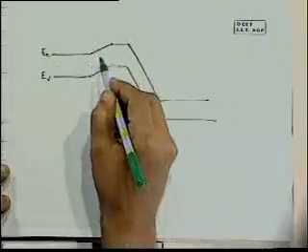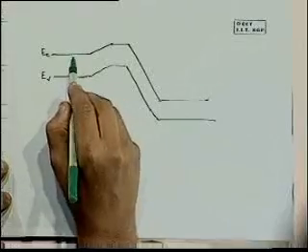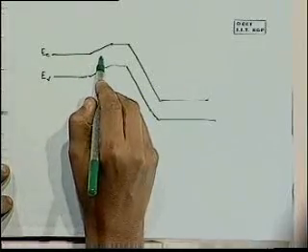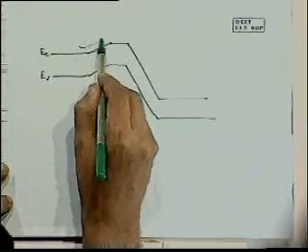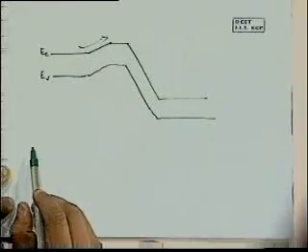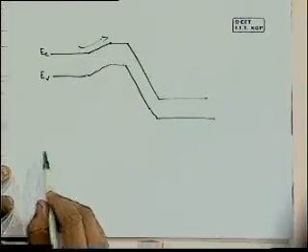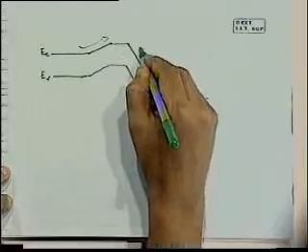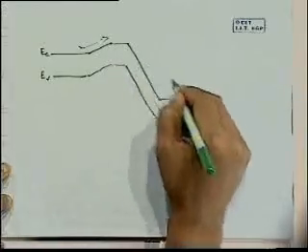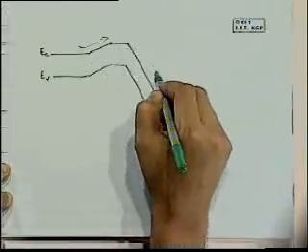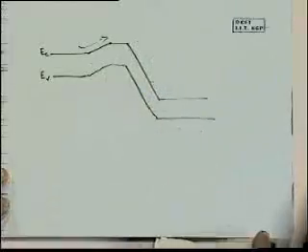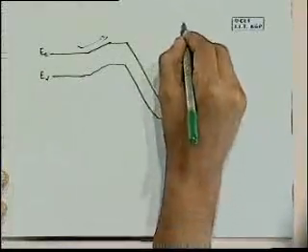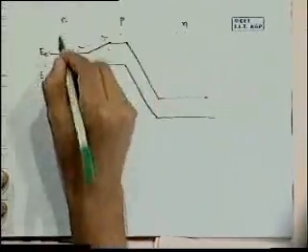And what we have now is that because the emitter base junction is forward biased, it's easy for electrons to go in this direction, right? And over here, because this junction is reverse biased, when it comes in here, it will be accelerated further. So let's call this the N, P, and N.